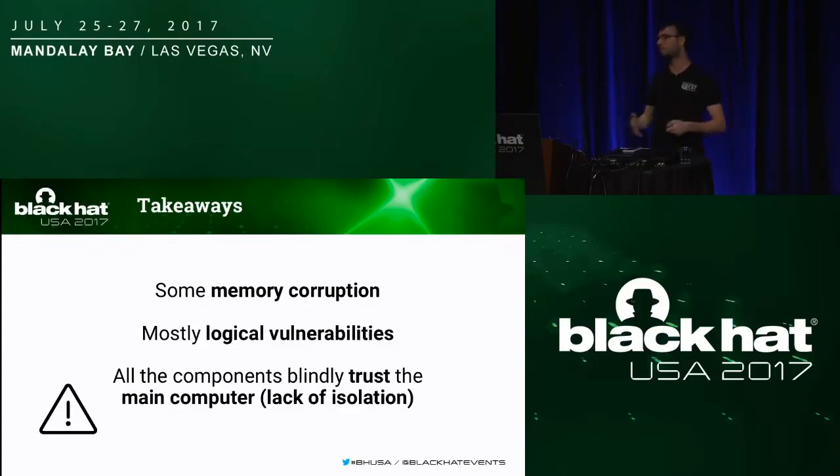But the main problem in our vulnerability assessment is that all the components are blindly trusting each other. There are no hardware or software trust boundaries between different services running on the main computer or different hardware components. So just a single stack overflow vulnerability in an unknown, poorly audited, not so important service of the main computer, and you can compromise all the components running on the robot controller because the components are trusting each other.